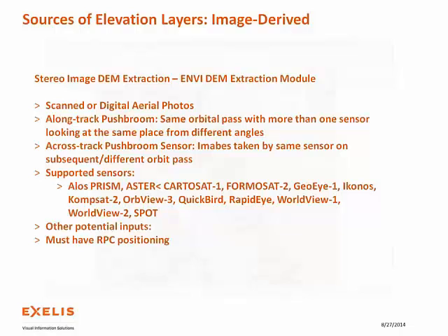And then a lot of times, if people use an image-derived surface, they can do things later down the road because what you end up with is just a lat long and a height. And you can do things like feature subtraction to get things off the surface to try and simulate bare Earth if you don't have real LiDAR.